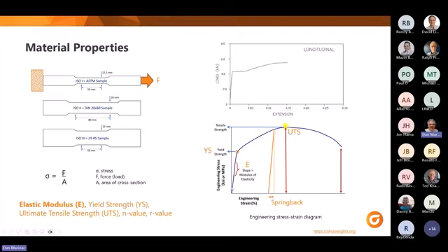When we strain a material all the way up the curve and all the way up to here, if we let go at that point, or we stop stamping the piece at that point, it will return and fall back in a line parallel to the slope, the elastic modulus, and it will fall back down to here. This distance here will be the amount of springback you achieve.